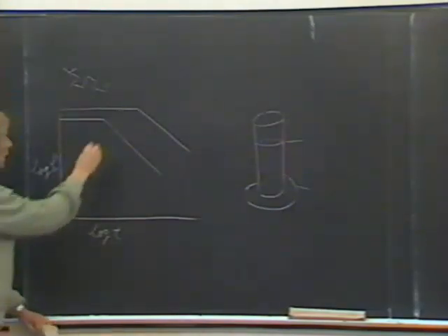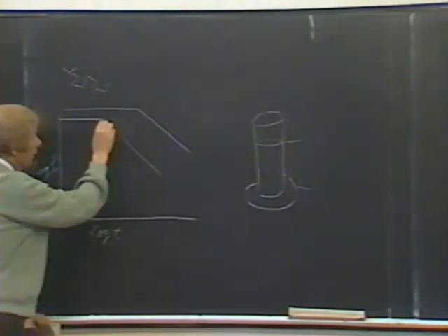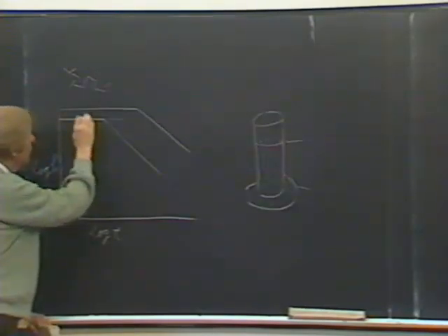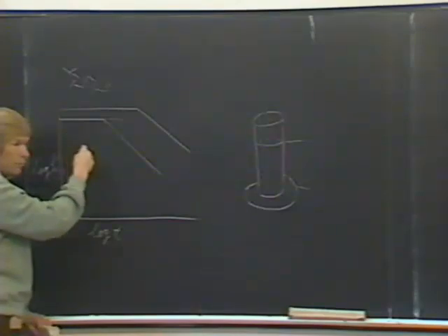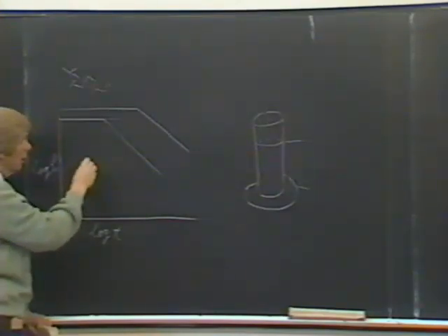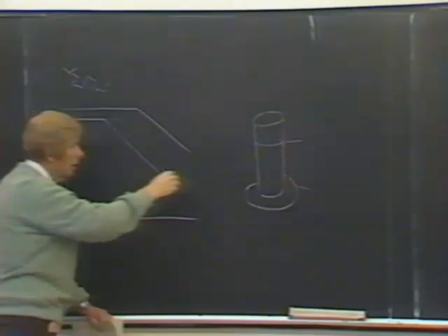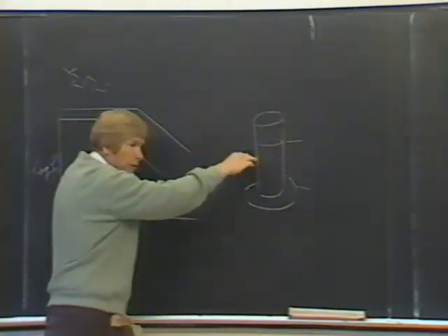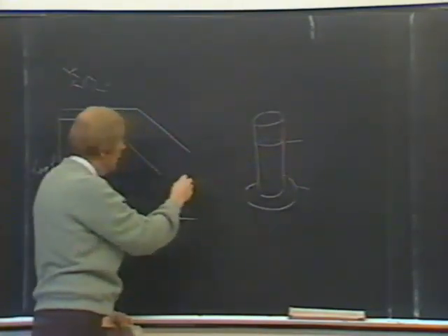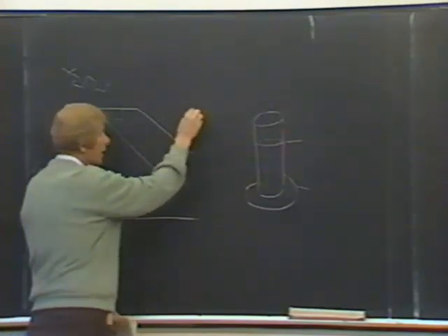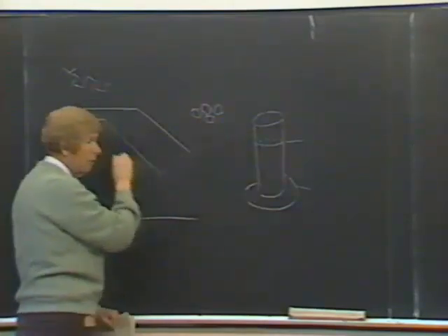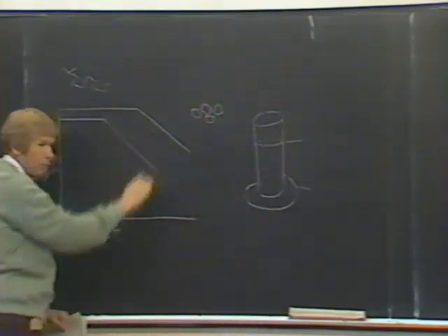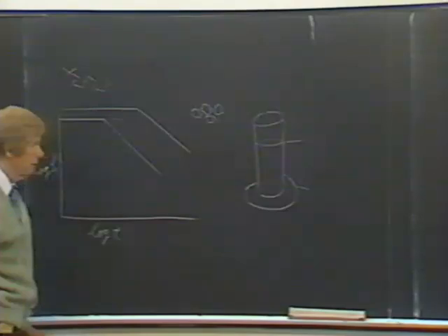What seems to be happening is that the unstructured material, slurry, rearranges itself under the gravity forces and thermal motions of the particles until there are local aggregates. That is, until they're with pores between them. Then at that time it begins to settle, and it settles in a kind of a consolidation arrangement.